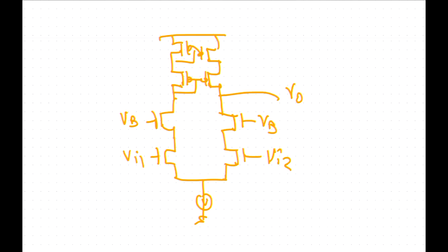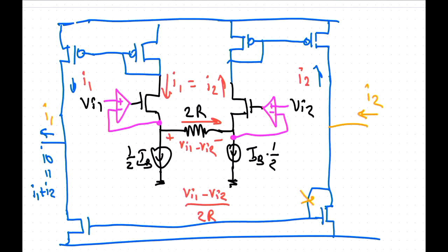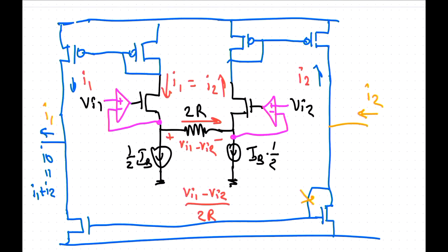You don't want them to be complex, because then you get more poles and then you slow the circuit down enormously. So they've got to be fast. And just a bit of gain is fine. So these are really the core. Probably the most common way to make a linear transconductor is by wrapping a resistor around a circuit, applying the input voltage across that, sensing a current in it, and then routing that out.